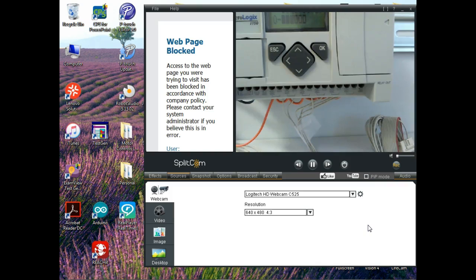We have one, I'd have to look up the name of it. It's basically flow charting. It's a really cool language. I played around with it a little bit, but it's another language that would be available. Of course, the predominant language, and the language we teach, is called ladder. Every one of them that I know of supports ladder logic. So a lot of times when you start off, you have to select the language that you want to program in. Most of the time, by default, these PLCs will default to ladder.